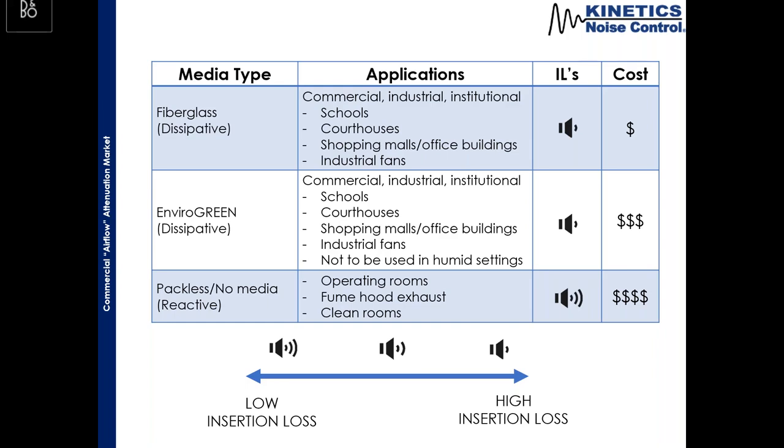When we compare this to the packless silencer, these are really specialized. The packless are usually reserved for things like operating rooms, fume hood exhausts where there could be some chemicals in the airstream, clean rooms, applications where we would want no fibers whatsoever in that system.